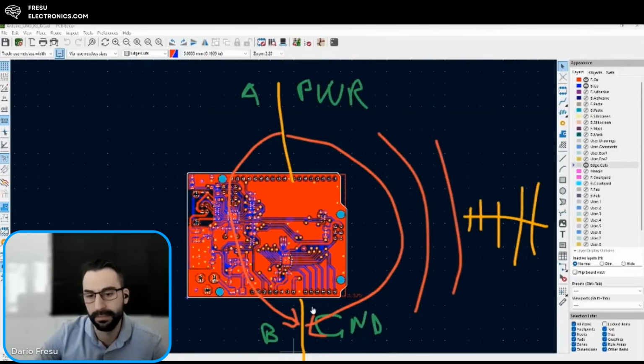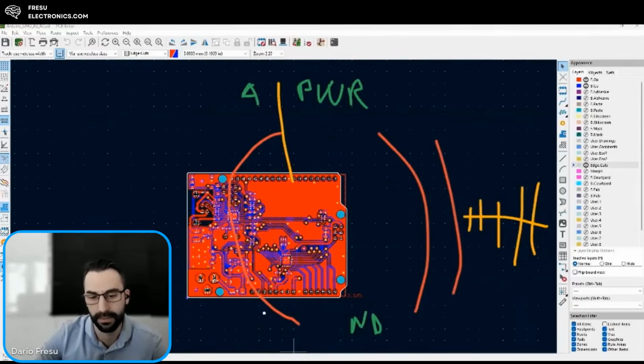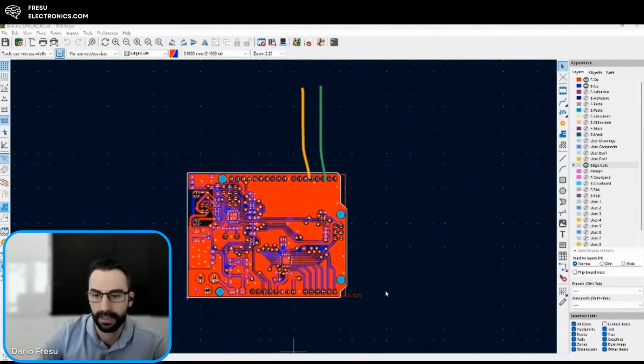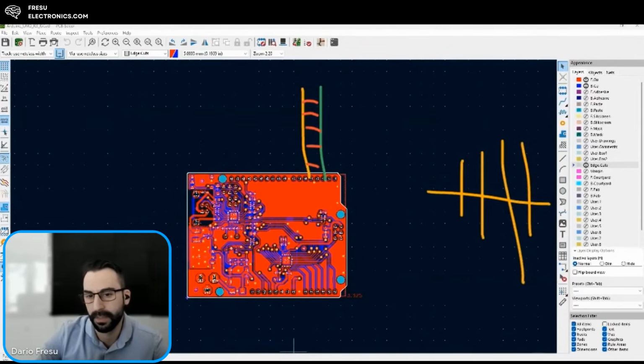So if instead I place these conductors in this way, where I have conductor 2 here, now how are the fields going to be established in this way? So if I try to pick it up with the antenna, what am I going to see here? Nothing, because I'm too far from where the fields are spreading. So people try to make it really complicated. It's all about field containment, and understanding that the fields are established in between the conductors.